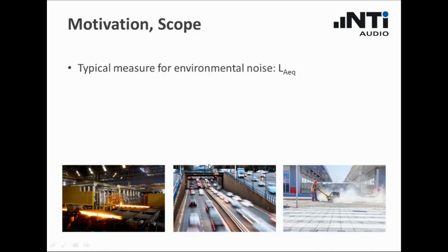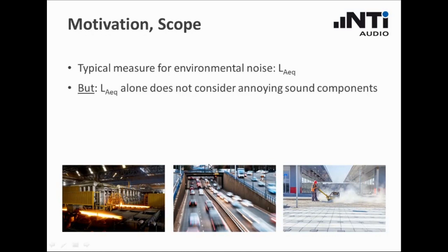The question, why do we have to introduce rating level or this assessment of the annoyance of sound, is quite obvious. Typically, when we measure the sound level of environmental noise, of industrial noise, we are using the A-weighted LAeq. However, this term does by itself not consider the annoyance of a sound.